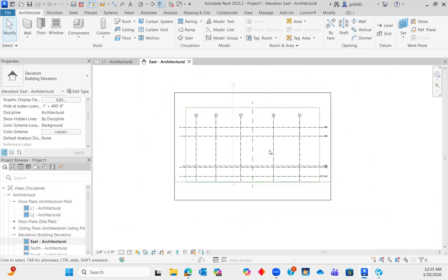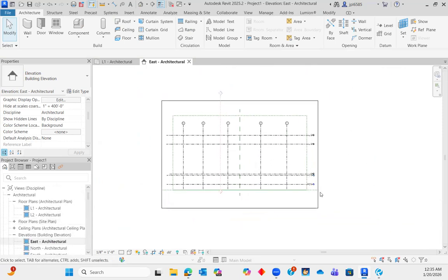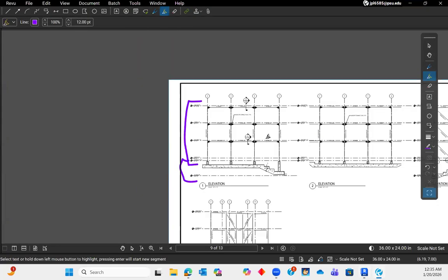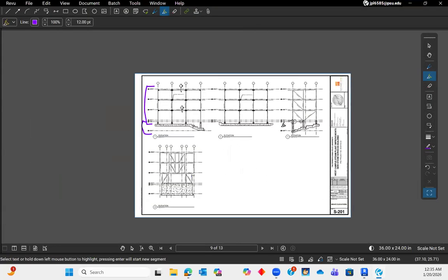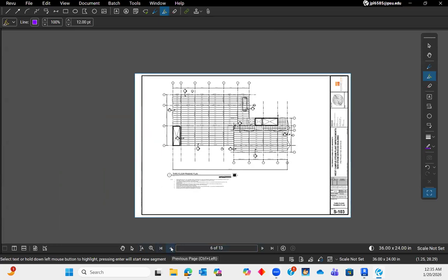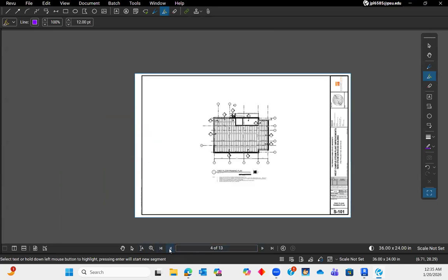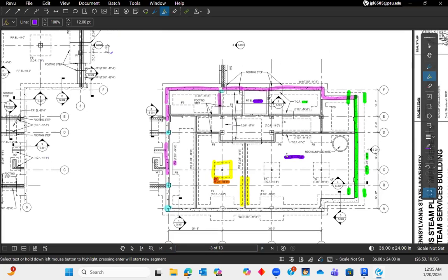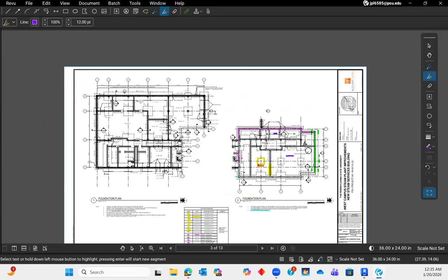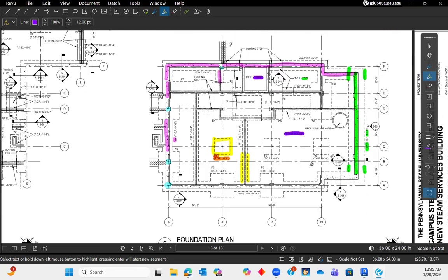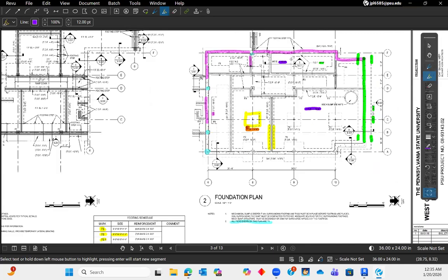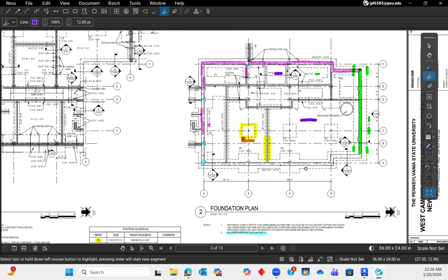So that means you guys will already be at kind of this stage. And I would just do all of your grid lines now and worry about just modeling the basement, but I would have all your grid lines done right now at this point. All your grid lines and levels done and dimensioned properly and locked in place so they can't move. And now we can get started on actually modeling the foundation.